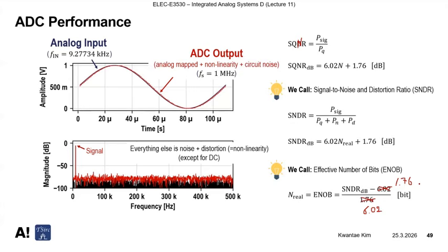So what it means is that we cannot just add in dB scale, right? Addition in dB scale means it's just multiplication. So first you need to do, for example, here, let's say this is one bin. Let's say this is minus 60 dB. Then first you need to convert to power domain. So convert all of these FFT results to power domain and add them up and take the ratio. Then you get SNDR.